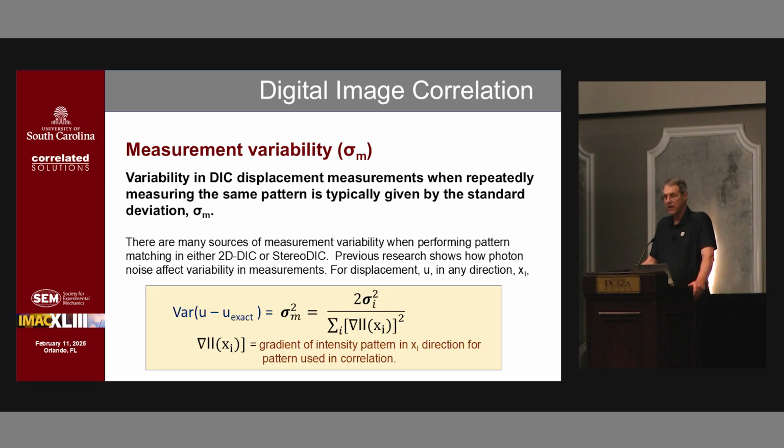So here, if the gradients go to 0, you can see how big your error is. It's infinite. So you can't be trying to predict what happens in an entirely black region. You won't have anything with any accuracy. You've got to have appropriate contrast in your image within the subset of the image so that you can extract good information.